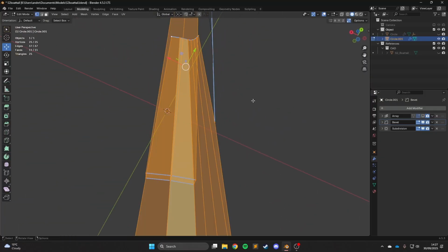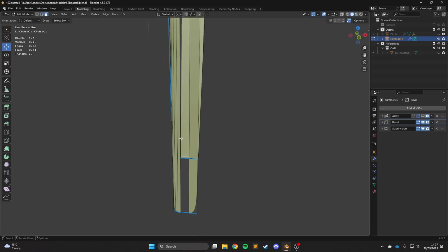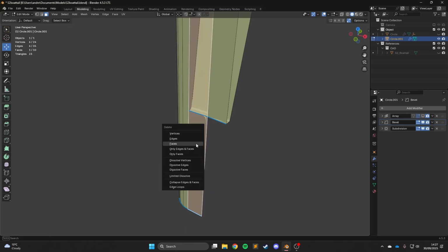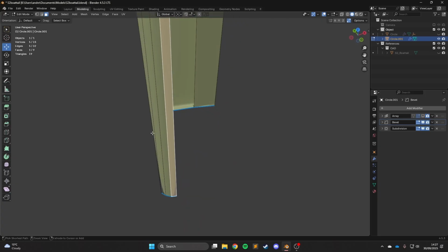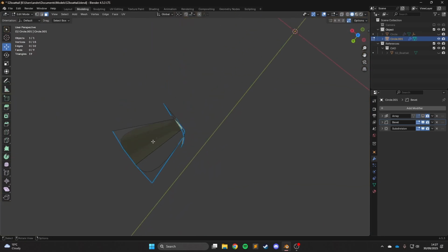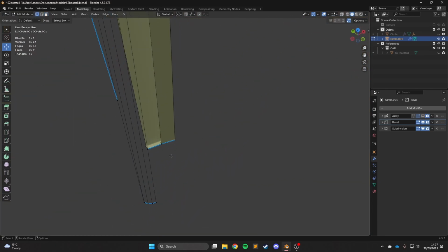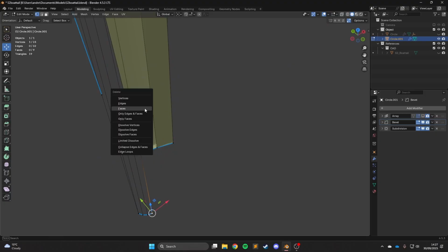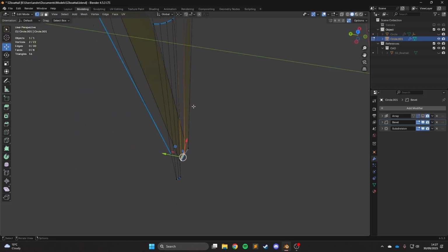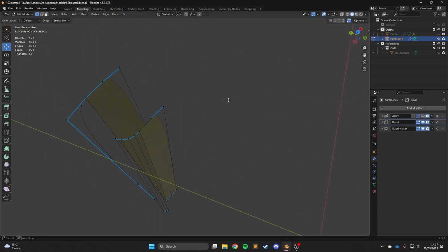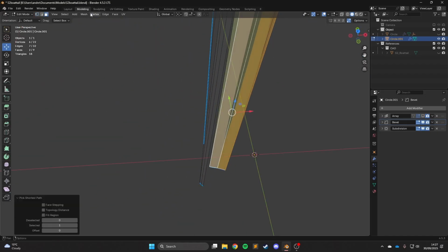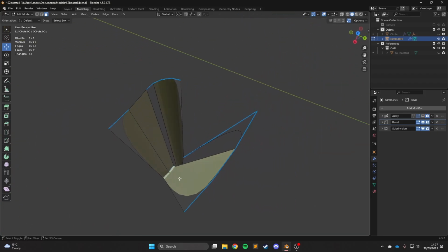So we have to put that back. Yep. And I'm going to get this face and get rid of it. This face we can also get rid of for now, and then these faces we just want to flip them. And there's no face there for now. Cool. So we're going to take this, get rid of that vertex there. And this is the kind of process of elimination here. We're just trying to get rid of the geometry we don't want. So we can connect that back up. I don't know where the hell these faces decided to flip on me. Flip these back. There we go.